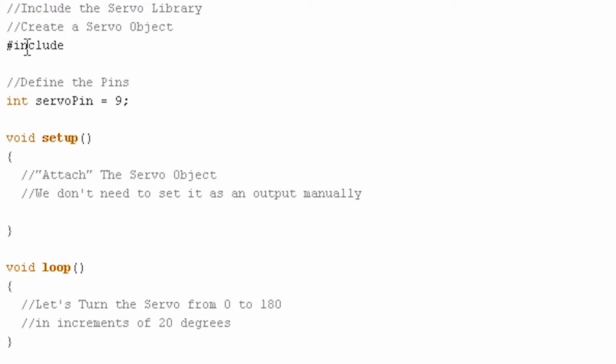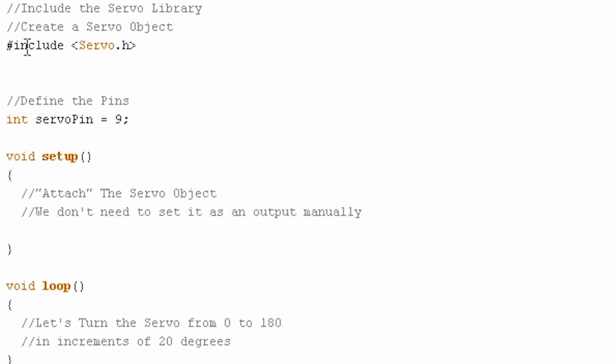The first thing you have to do is include any optional libraries that you want to use. So we'll include the servo.h library. You can learn more about all the libraries available to you on the arduino.cc website. After we include the files that will allow us to interact with the servos, we'll need to make a new servo object that we can control. To do that, you type Servo and then whatever you want to call the servo. I'll call this one Jeremy's servo. This is creating a new object called Jeremy's servo of type Servo. Now we can do stuff to that.